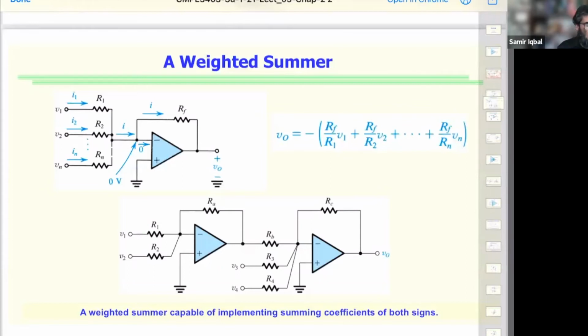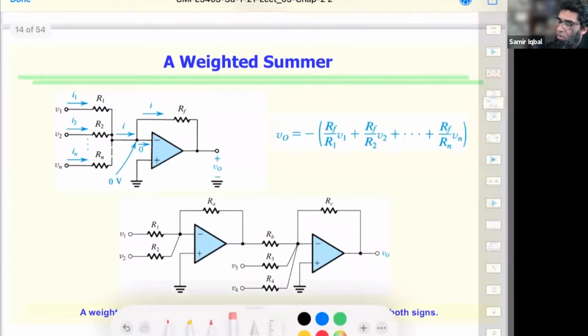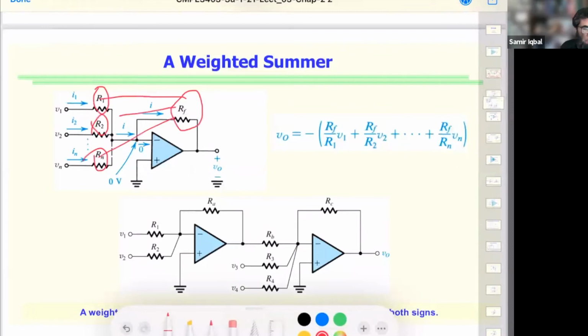What we are doing here is there's one feedback resistance in the negative feedback, and that has to play a role with each one of these resistances now. So this and this, this and this. So what we end up doing is then finding all those number of input signals and adding the current contribution from all of those, but those have to be weighted.